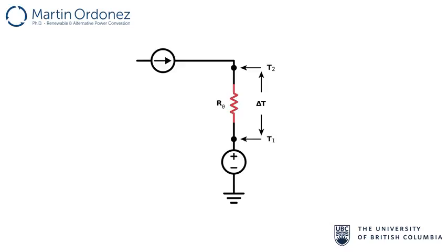In order to solve the thermal problem and find the junction temperature value, as mentioned before, we need to know the thermal resistances and the power losses, which act as the thermal source. For determining MOSFET losses, you can watch our video on power loss calculation. However, for this example, let's consider 6 watts of losses.